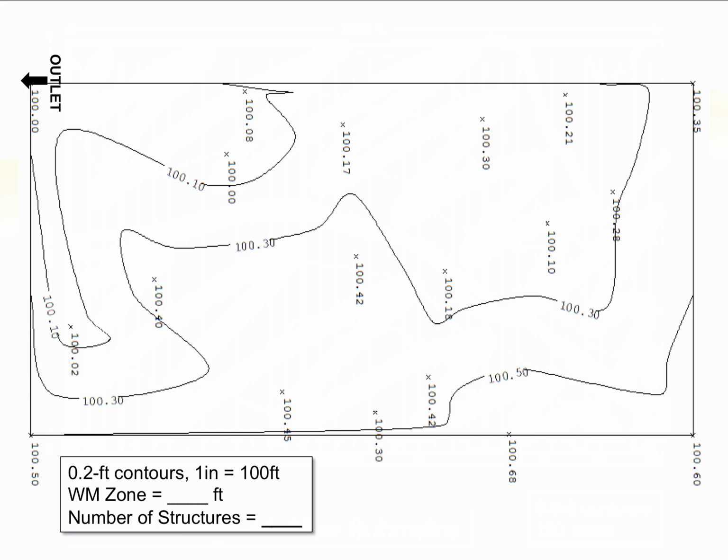At this point, it really doesn't matter what kind of drainage layout is on this field, where the laterals go, where the submain goes, because one structure can pretty much pick up the entire field. Now, if this happened to be a pumped field with a pumped outlet, that pumping point, that lift station, could in fact be the control point for this field as well.